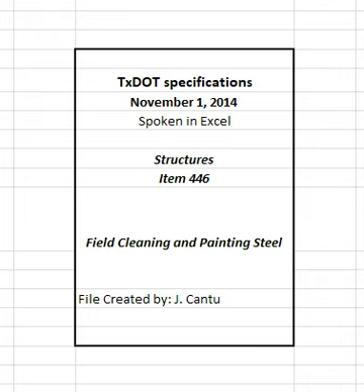SSPC Guide 6, Class 1A, Level 1 emissions. Ability to withstand winds up to 30 miles per hour. Enclosure of all sides of area with air impenetrable walls. Illumination meeting SSPC Guide 12. Rigid, watertight floor formed from minimum 20 gauge steel.